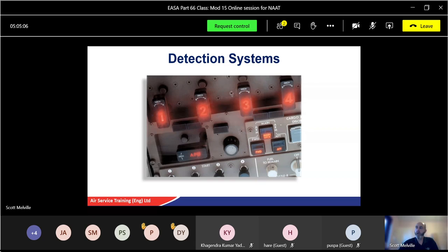And detection systems, like we've got here, we've got guarded numbers for each engine. They will light up, saying there's a fault, so a signal from the detector will illuminate, and you'll get the audible sign as well. Continuous indicates temperature conditions in the engine bay and may be used to operate the alarm bell or the audible warning device at the warning temperature. Test facilities test the continuity of the system. So, press to test facility, just like an APU.